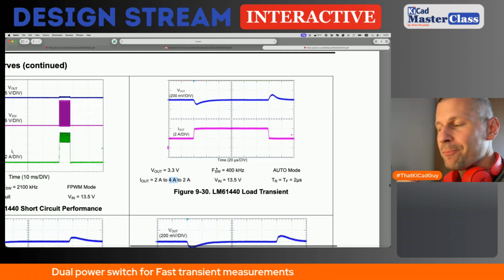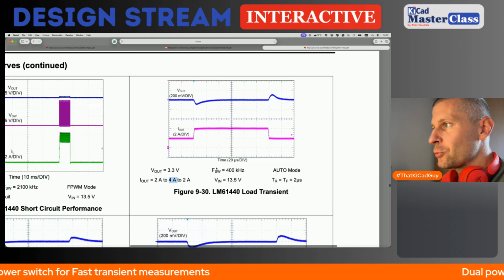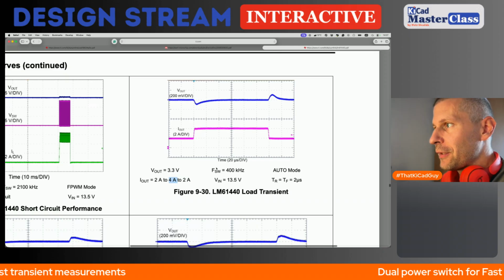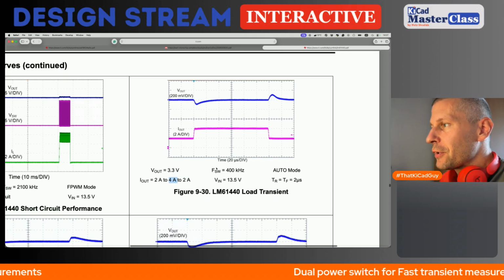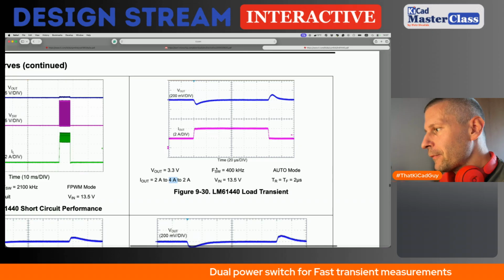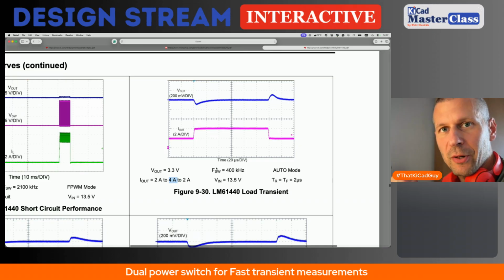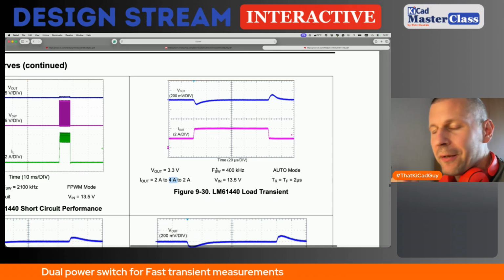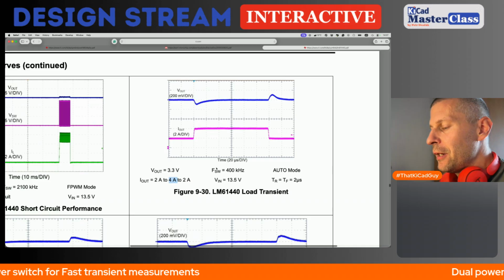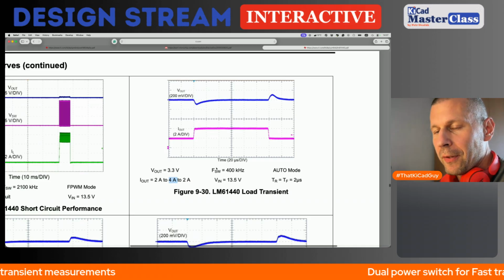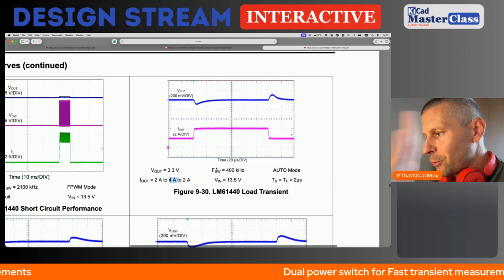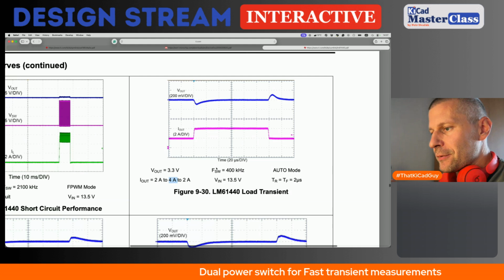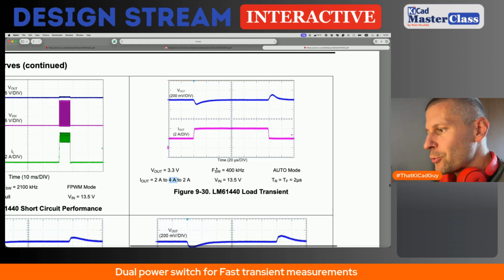my switch is not ideal. It's too slow, and there is quite some inductance in the PCB traces. Frankly, it's not a PCB, it's a universal board with bottom layer soldering, so nothing nice to see, nothing nice to use.